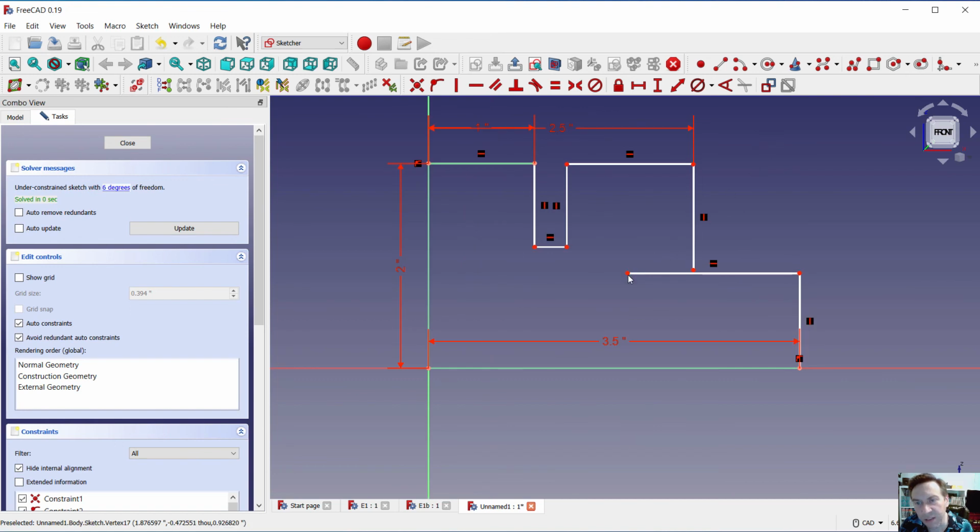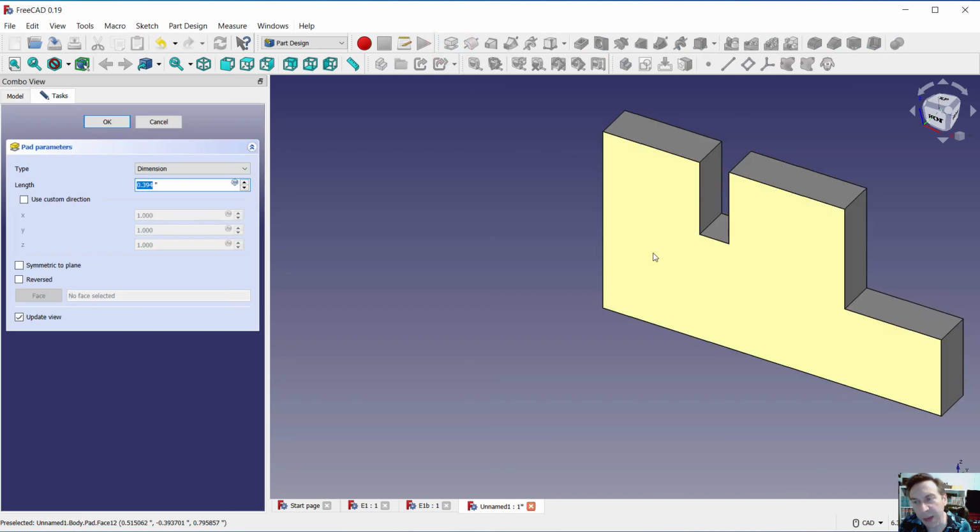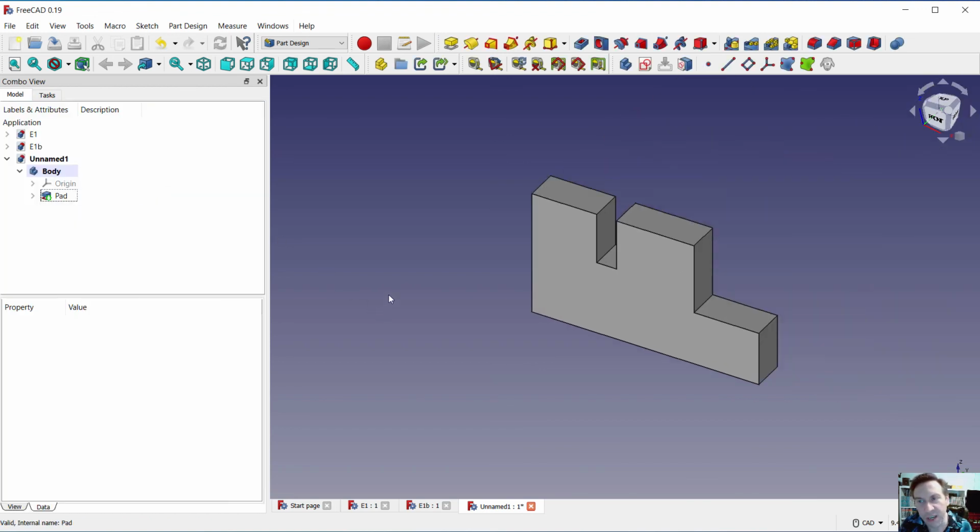All right. Now, let's see if we can drag this over, because see, I can drag it there, but it's not automatically aligning, so that's where we use coincident. There we go. All right, and then we would continue to add. I'm going to hit escape here, and I'm going to drag this up and stack the dimensions as we see them. I'm not going to go through all these. I'm just going to now hit close, because I think we have a boundary which we could use pad for. Click on pad, and there it is, and we set it to 0.5, hit enter, and we have our geometry.